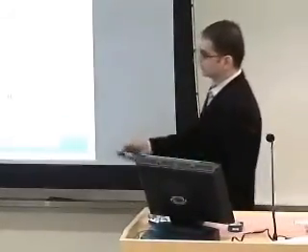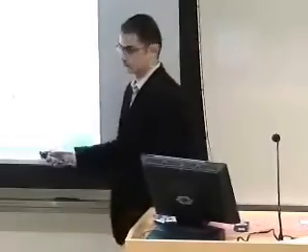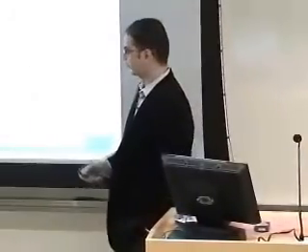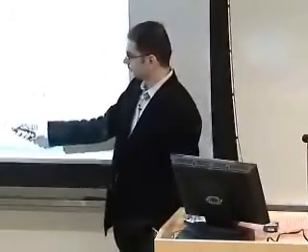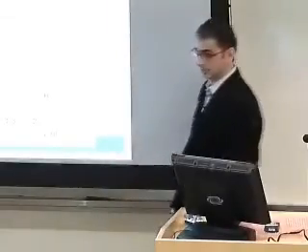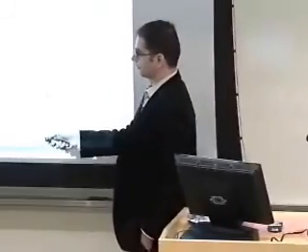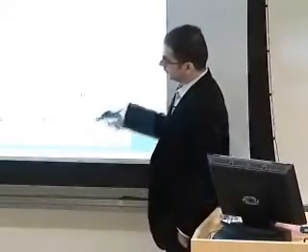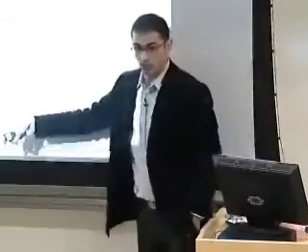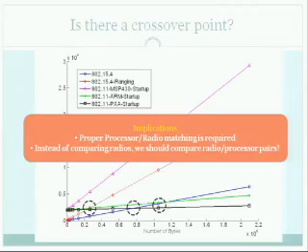And now you can start seeing the actual trade-off, the actual sweet spots between the 15.4 radio and the actual Wi-Fi. So here, above approximately 1 million bytes, it makes more sense, it's more energy efficient for your system to use the Wi-Fi radio rather than the actual 15.4. And of course, the faster the processor we use to control the Wi-Fi radio, the smaller and smaller the sweet spot becomes. Yes? Small packet sizes, you just want to use the Zigbee and nothing else matters?